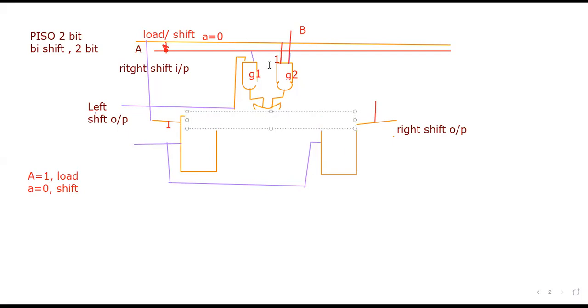Then after, once you draw this, you have to give names over here. It is JA, then Q. Here it is JB and Q. And as it is a register, we have to compulsorily draw inverted input to the next one.